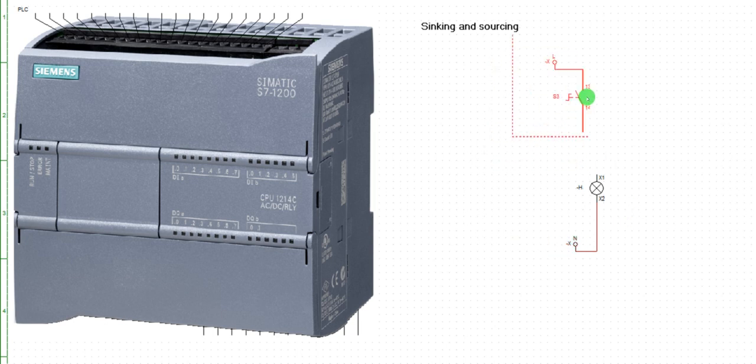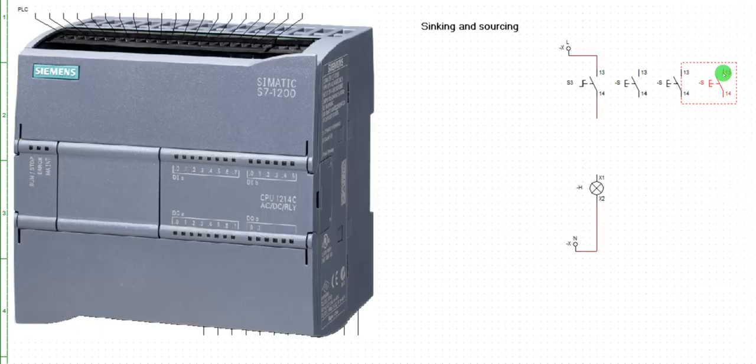Now the PLC CPU demands that since this is the supply, this is my live conductor going to my input bit. If you have multiple inputs like this, you're going to line them up this way. All of them must come from your supply. So if I have something like this, the whole of this is going to be my input, going to input bit 1, 2, 3, 4.